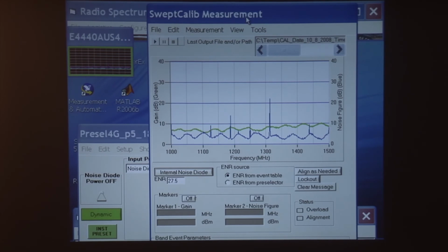And we wanted to show you this today to help bring home this lesson: the important thing to keep in mind when designing any kind of measurement system or looking at the performance of any kind of receiver is that it's important to use the Reese equation that we talked about a few seminars back to optimize the noise figure and the dynamic range of the measurement system both, and that more gain in an amplifier is not necessarily a desirable factor to have when you're making a measurement. It's not having more gain, it's having the right amount of gain, typically optimizing the gain factor against the noise figure.